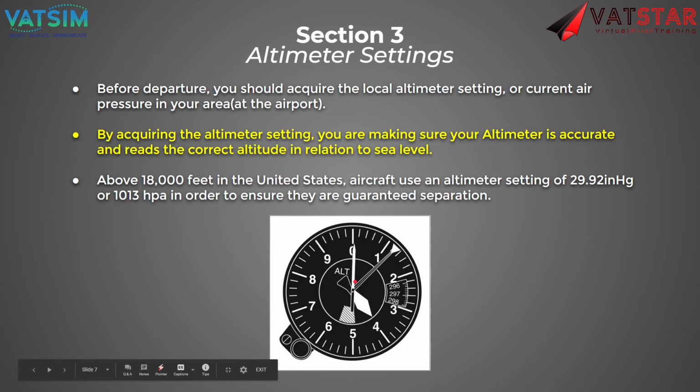You might be asking, how did I know I'm at 14,000 and not 4,000? Well, if I was at 4,000, this triangle here would actually be below the 1. So this triangle indicates the altitude in tens of thousands of feet. So I know I'm at least 10,000 feet. I'm at least 4,000 feet, so I can combine those two. I'm at 14,000 feet. And I know I have no hundreds of feet, so I'm at an even 14,000 feet. I hope that makes sense to everybody on the YouTube video. Please comment if you have any issues with that.